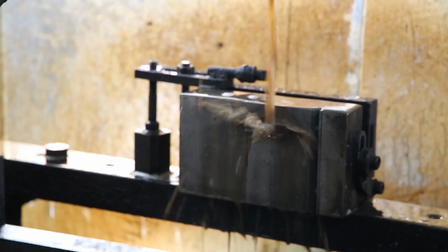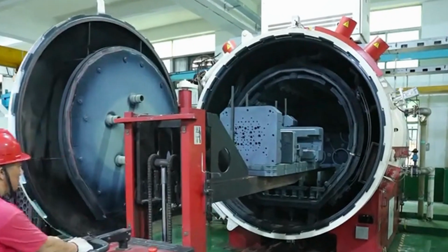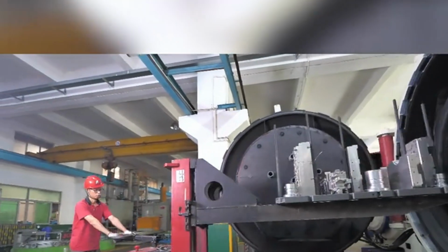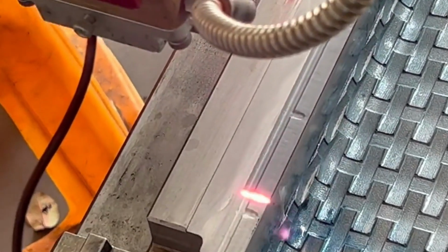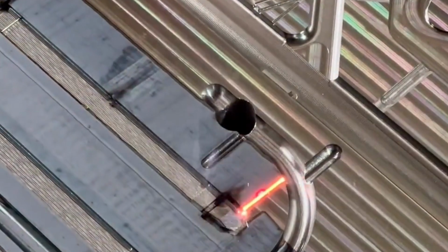During the trial molding process, some problems may be found, such as flash, sink marks, and dimensional deviations of the parts, and the mold needs to be adjusted and optimized. According to experience, generally, the mold needs to go through 3 to 5 trial moldings to achieve the ideal molding effect. After the product is put into production, it is also necessary to continuously improve and optimize the plastic molded parts, and the mold according to the feedback during the production process and market demand.